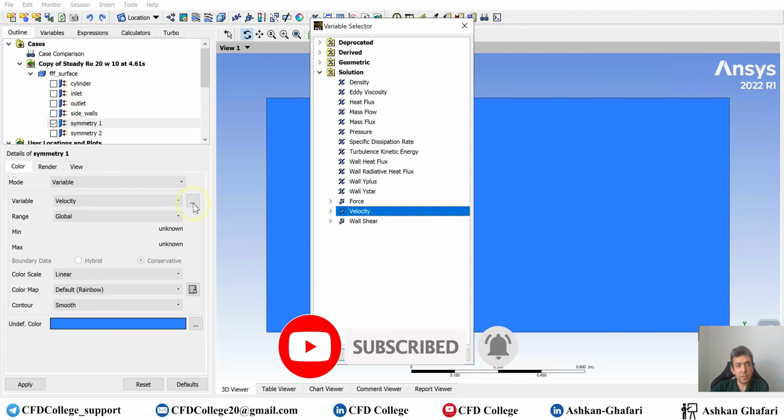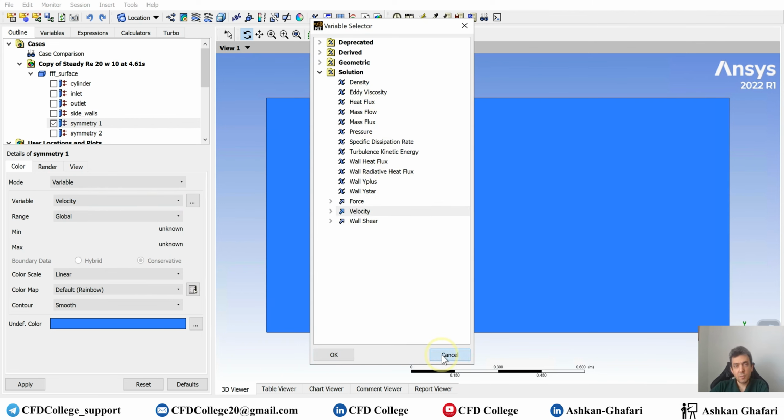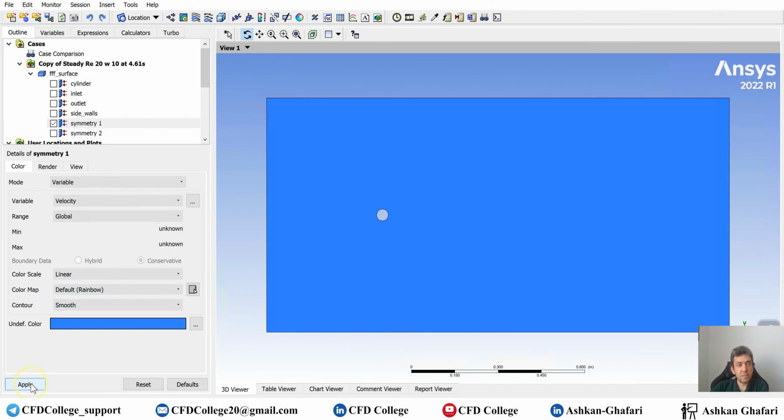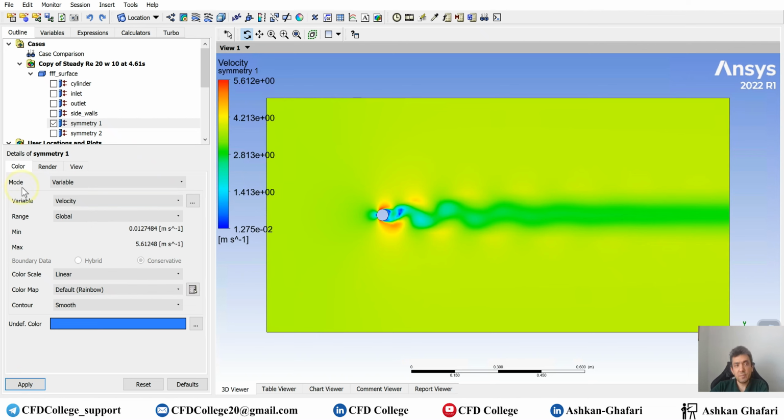We only have these quantities. You can create Z vorticity, but you need to use expressions. So if you want to learn about expressions and creating new variables, please watch the video which is related to that in the CFD-Post playlist. The maximum velocity is 5.6.